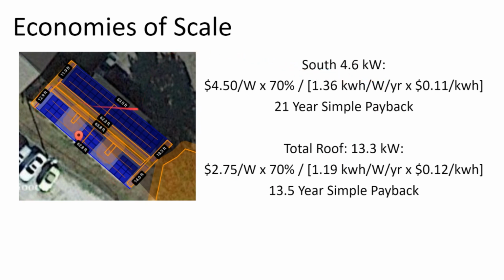The complexity of the roof is as important as the roof tilt or orientation. A walkable roof maxes out at a 5/12 roof pitch. The steeper the roof, as well as the height of the roof, as well as the type of roof, can substantially increase the project complexity and cost.